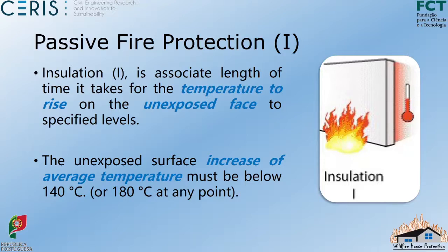For example, imagine you have bolts or a small connection. But in any case, we normally look at 140 degrees. So the unexposed surface must not have more than an average temperature of 140 degrees.